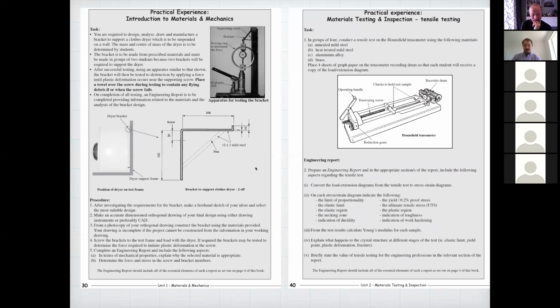Then I'd put a fairly heavy towel on top of the window. And then I'd get a wooden mallet. And then I'd ask a student to only hit it with 50% of his power, because we don't want the thing to explode. And anyway, he'd try and break it with the mallet. And then he couldn't break it. And then I'd give him a bradawl, and I'd just get him to hold the bradawl on the glass, and then tap it, and the thing would explode. And then I'd be able to explain that it's been thermally toughened.